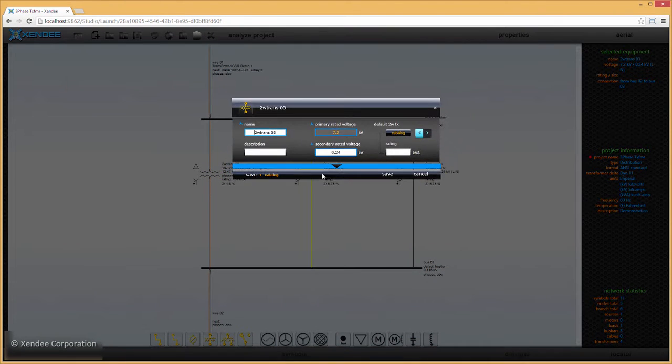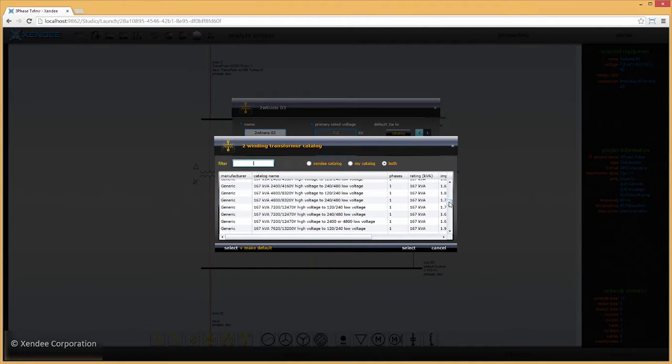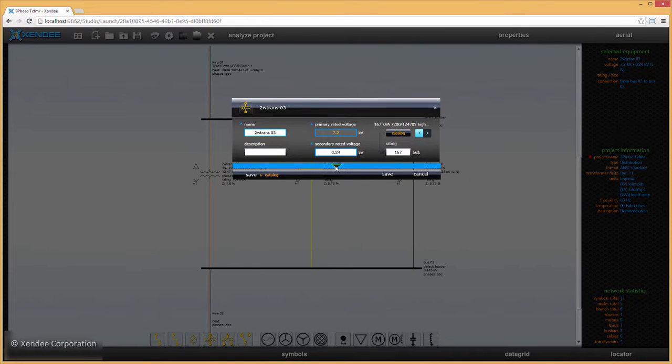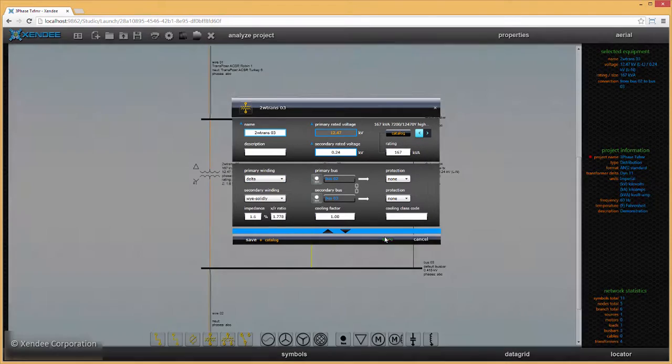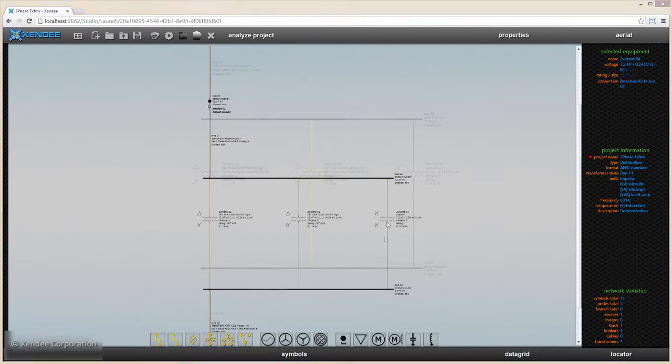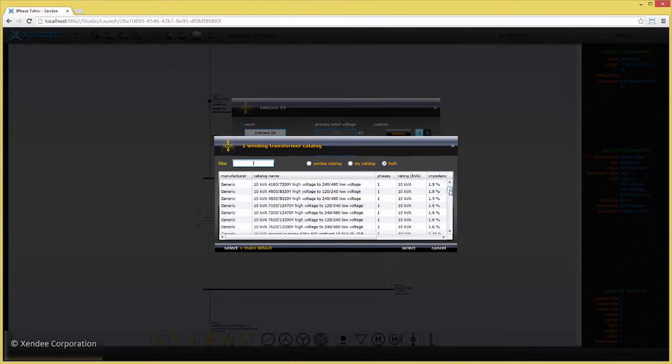We will need to go ahead and define the other two transformers the same as our phase A transformer. Note that the winding types and voltage ratings on transformers in parallel must be identical, and ideally they should have the same impedance and tap settings. If you want to explore different tap settings or impedances for each phase, OpenDSS can handle it, and you can get really creative, but please be prepared to correctly interpret the simulation results.